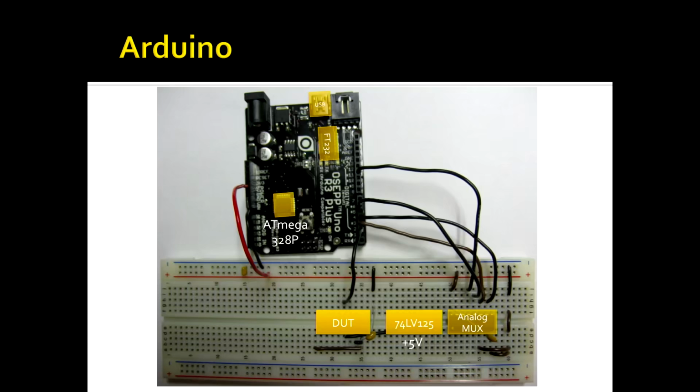It automatically goes through a divide by 2 as soon as you turn any of those timers or compare features on. So before I even started, all I could do was 8 megahertz signals out of this thing. If your device is running at 2 or 4 megahertz, that might be enough. But if your device is running at 32 megahertz, then obviously this isn't even going to help you. So it just wasn't flexible enough.